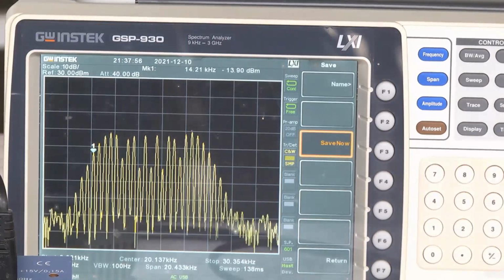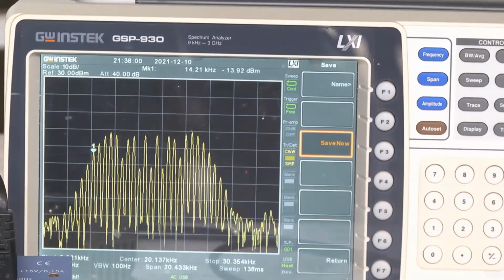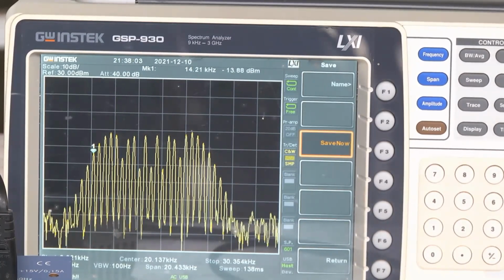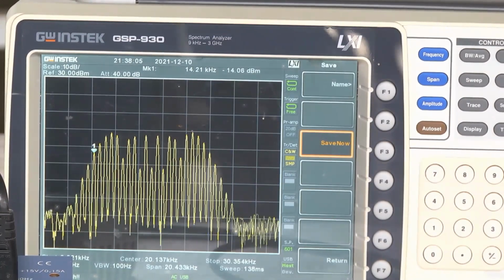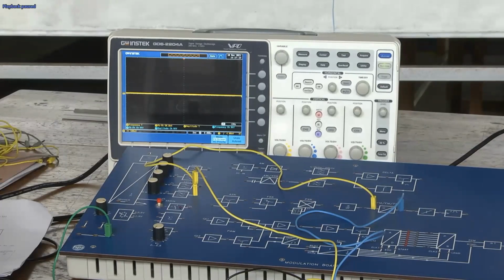Okay, now here we kept the frequency at 500 hertz and we vary the voltage from 0.25 to 0.5 and then 1 volt. For all three voltage values, we check the output waveform for the 500 hertz input signal. Then now we have to take the 1 kilohertz input and check the output signal for the 3 voltage levels.